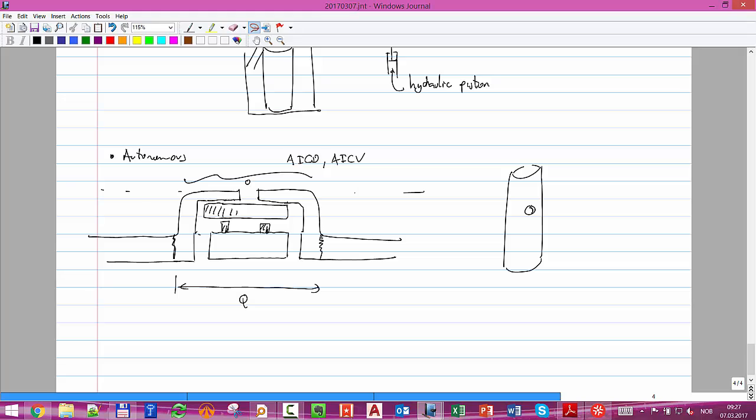It's going to separate, but it's going to become a bit closer to the upper wall when it has gas and when it has water. So if you see the opening, which is that distance between these two, the opening, let's call that H, changes depending on the fluid circulating.